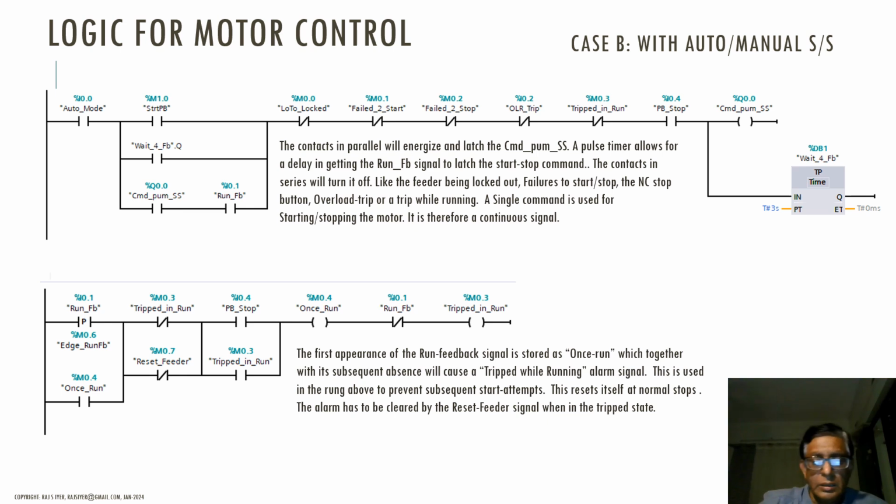It can be any other signal derived to say that the machinery is in motion. Okay, a pump is pumping water, or a gearbox that is driven by a system of belt and pulley. The belt is not broken; it is moving. Okay, if the belt breaks, you will lose the run feedback. Okay, so this is for detecting these things.